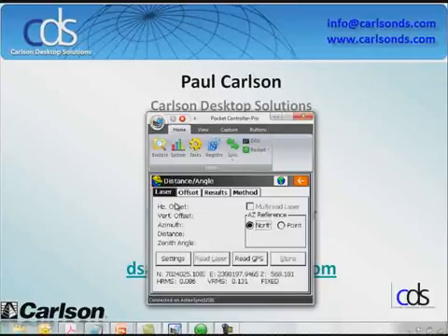The nice thing is, in my coordinate file, in the CRD file, all I see is the point. Here's where it is. In the raw file, I see the offset information that was calculated. I say this 1,000 times in SurvCE classes that I teach: that raw file is my field book file. It's my electronic field book, essentially. And all of that good information that I should be writing is stored in there, including in the case of offsets.